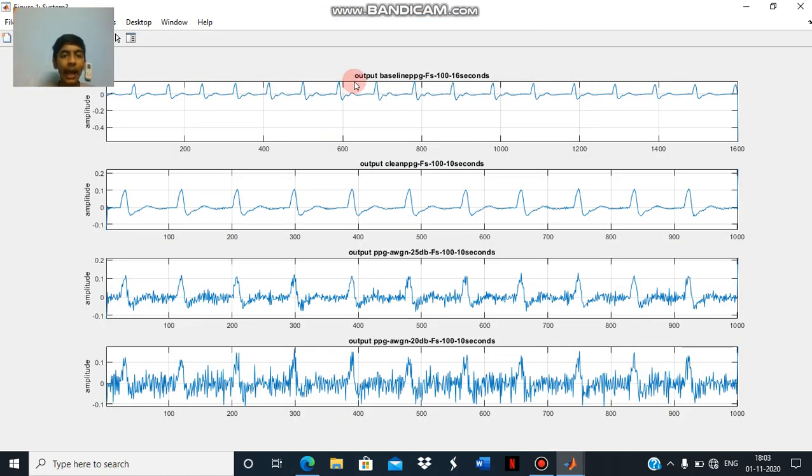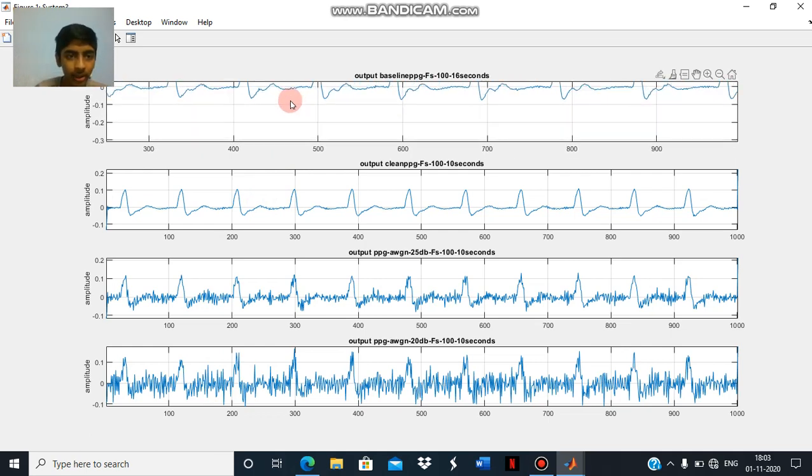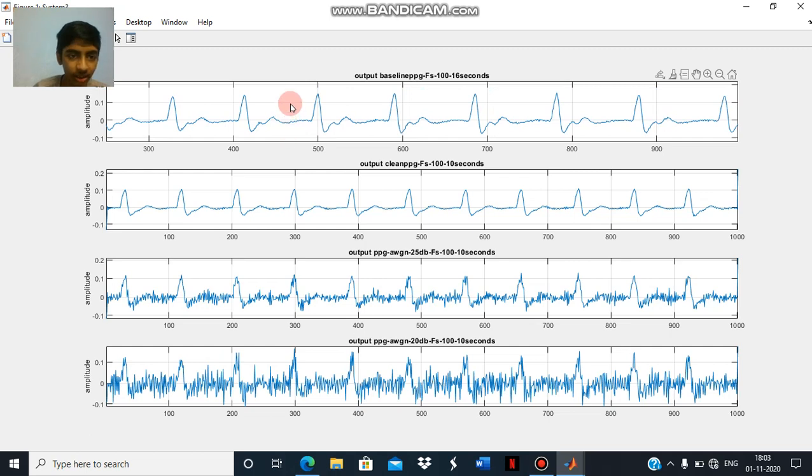So here, unlike systems 1 and 2, we can clearly observe that the disturbances have increased. When I zoom the curve, initially input signal 1 has zero disturbances and there are no fluctuations, but here we can clearly observe the fluctuations have increased, so the noise in the signal is increased. By this we can say that system 3 is a noise adding system, and by looking at it, it is a differencing system, which is a high pass filter.